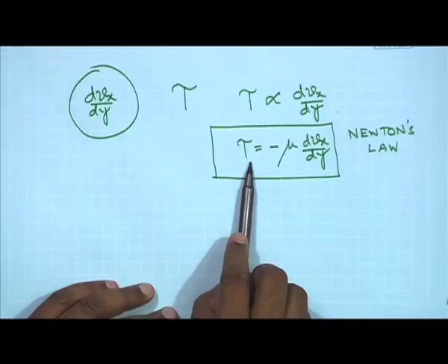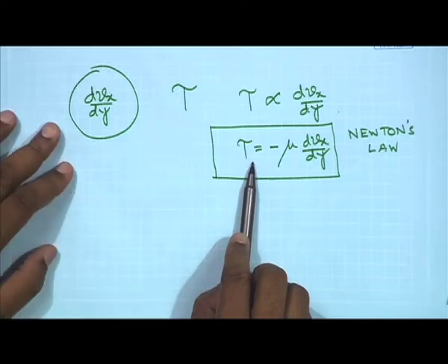There can be pseudoplastic, there could be dilatant, where the variation between the shear stress and the velocity gradient cannot be equated by a simple equality by imposing the parameter mu. So this brings us to the question of which direction this momentum transport is taking place.